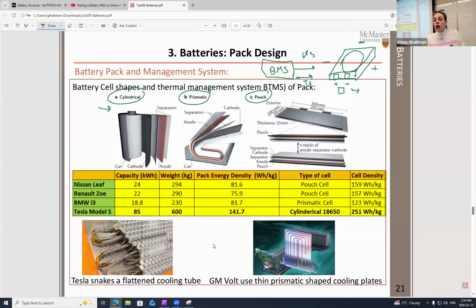This is super important because sometimes having both of them on top causes accumulation of heat in this region, and it may cause an unsafe situation for the operation of the battery, specifically while the driver is driving, and may cause some danger. Therefore, they are studying, for that certain pack, whether it is better to have the regular format, meaning both tabs in this location, or move the location of the tab to another direction. So far, so good. Any question?